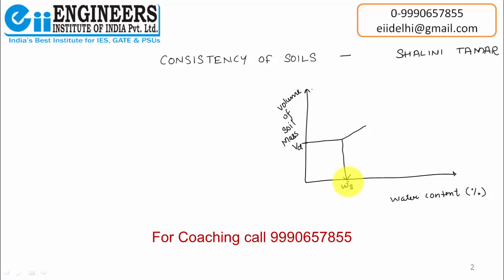So I can say that shrinkage limit is the minimum water content at which reduction in the water content will not cause decrease in the volume of soil. Now what will happen if I increase the water content? There will be a value of water content at which soil will start behaving like a plastic material. So after a stage, my soil will behave as plastic. That limit I have denoted as WP.